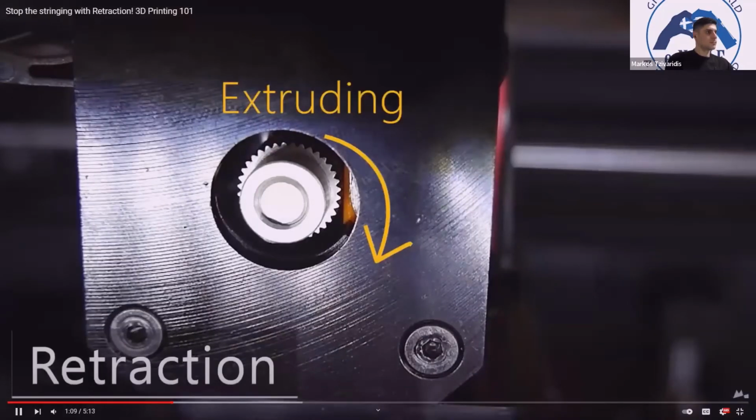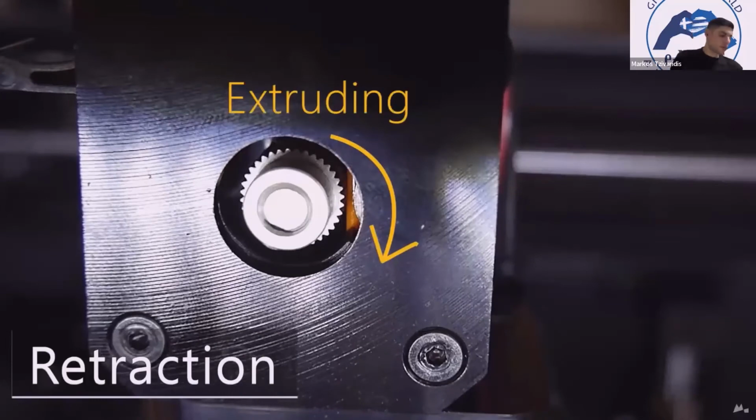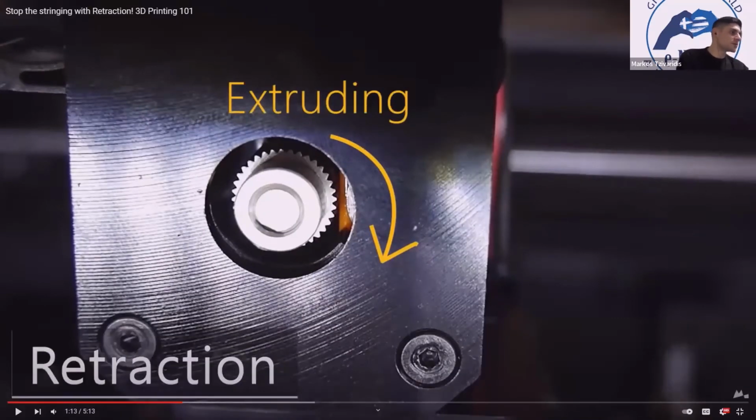Well, this is called retraction. Retraction actually pulls filament back up from the hot end. Let me show that again. So this is retraction, guys. The extruder takes the filament back inside the nozzle. So at the moment that I move from the first cylinder to the second cylinder, I retract the filament back in the nozzle. So the melted plastic will be inside the nozzle and not melt down when I'm printing.